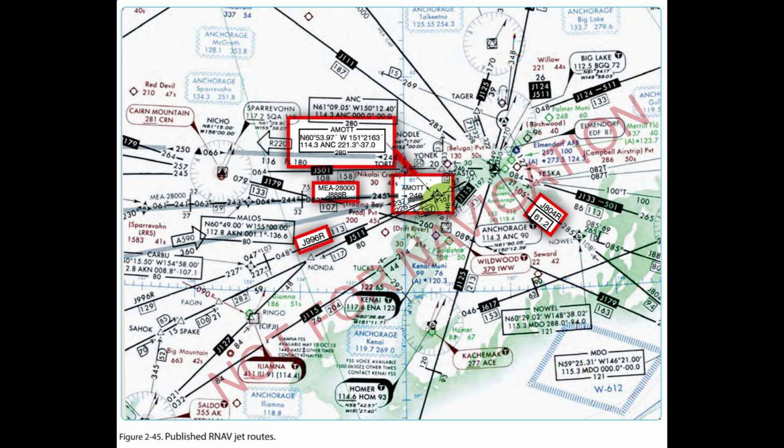The published RNAV route designation may be obvious, or, on the other hand, RNAV route designations may be less obvious, as in the case where a published route shares a common flight track with a conventional airway. Note, the use of RNAV is dynamic and rapidly changing, therefore, en route charts are continuously being updated for information changes, and you may find some differences between charts.